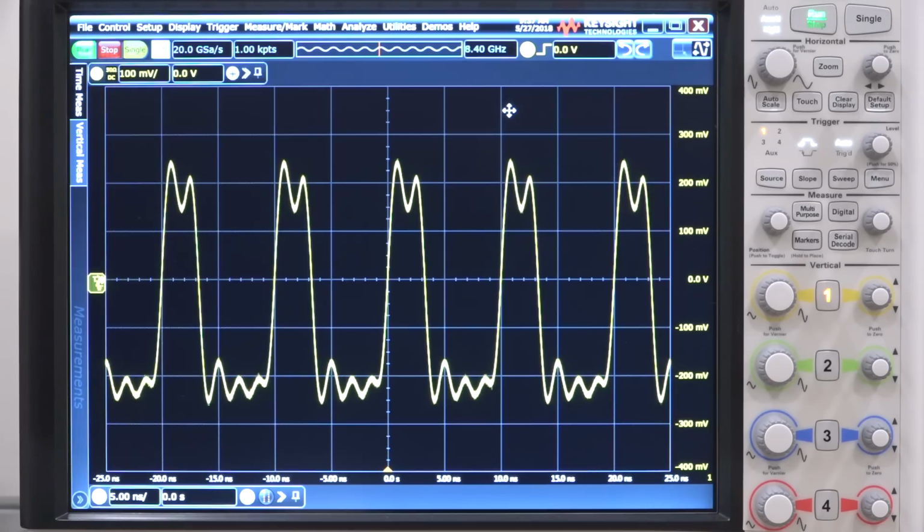And just to show you that it is indeed possible to fix this issue by playing with the settings, all I did was set the second channel to the exact same settings, and I re-uploaded the waveform by enabling channel 2, and as you can see, the waveform no longer does that. So it's fixable. Now let's jump to the spectrum analyzer.